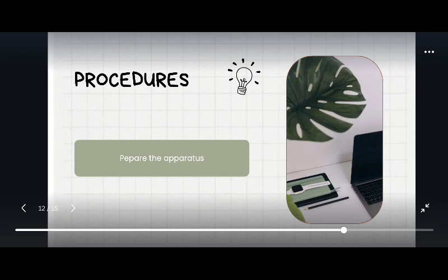Take a sample using the spatula from edge to edge of the soil pad. The sample should include the soil on both sides of where the groove came into contact. Place the soil into a moisture can. Immediately weigh the moisture can containing the soil. Record its mass and place the can into the oven. Leave the moisture can in the oven for at least 16 hours.